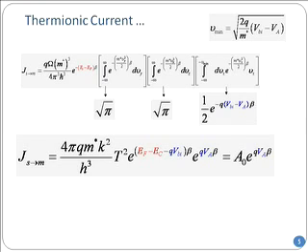On the other hand, here, I do not have the band gap explicitly sitting there. Of course, band gap is hiding somewhere, and we'll talk about that in a second. But in general, since there is no Ni squared term, although the expression looks almost the same, it is much less temperature sensitive. Now, you should try to work it out, because I have just shown you a square root of pi over there, but I haven't accounted for all the constants that we'll need. Do this when you go home, and you will try to see whether you can pick up all the constants.